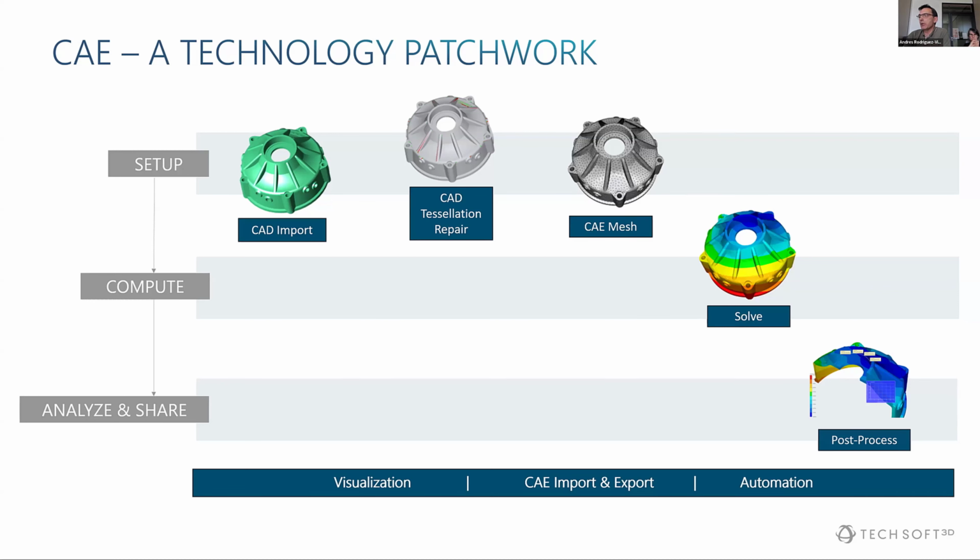So it seems like a little step, but the CAD tessellation repair or mesh healing is a time-consuming one. So having some technology there to help out, to automate, is quite important. Once the tessellation is compliant, then you can feed that into a mesher.